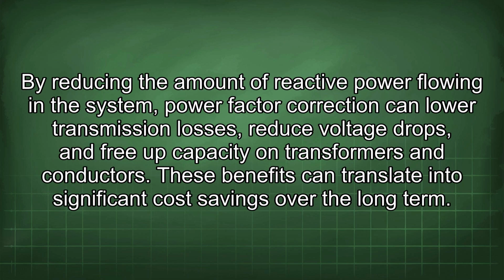By reducing the amount of reactive power flowing in the system, power factor correction can lower transmission losses, reduce voltage drops, and free up capacity on transformers and conductors. These benefits can translate into significant cost savings over the long term.